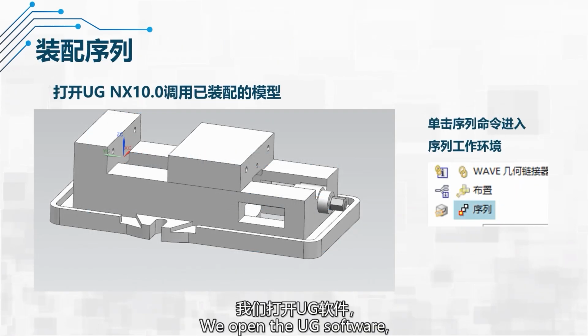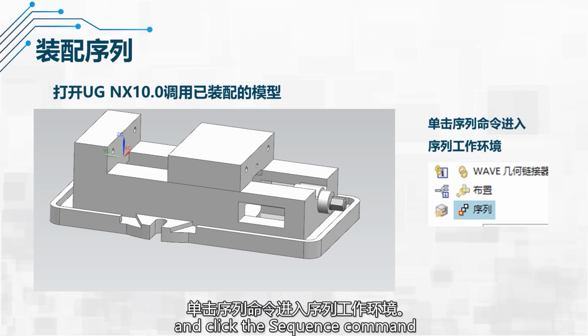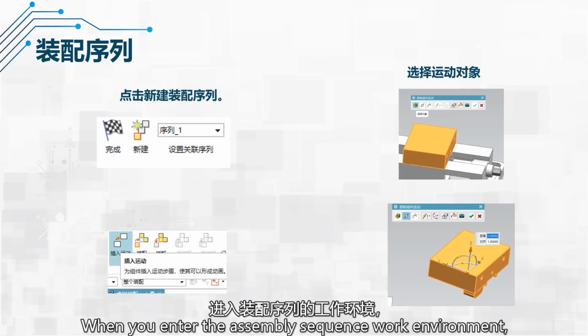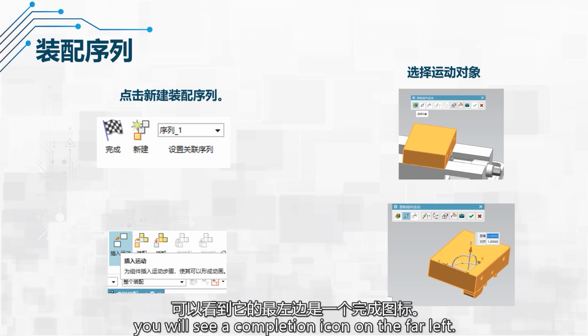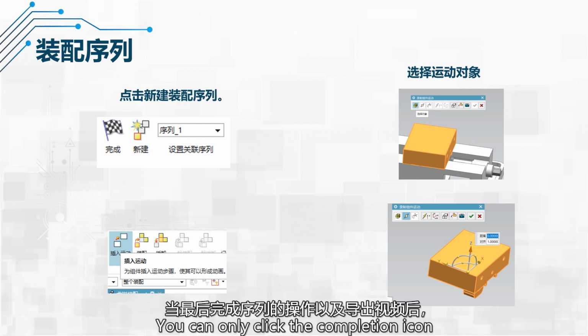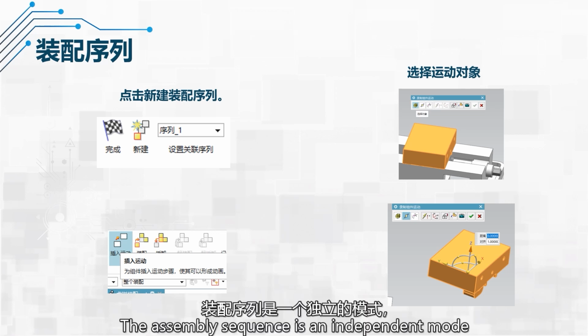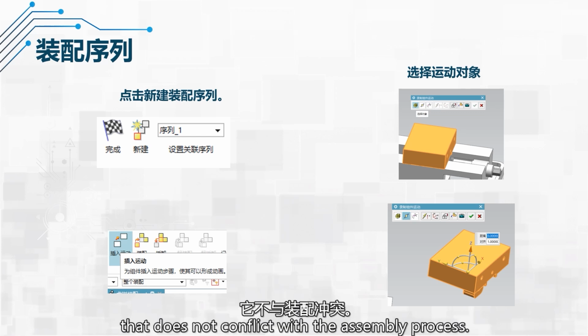We open the UG software, import an assembly model, and click the sequence command to enter the sequence work environment. When you enter the assembly sequence work environment, you will see a completion icon on the far left. You can only click the completion icon and exit the operation after finishing the sequence and exporting the video. The assembly sequence is an independent mode that doesn't conflict with the assembly process.